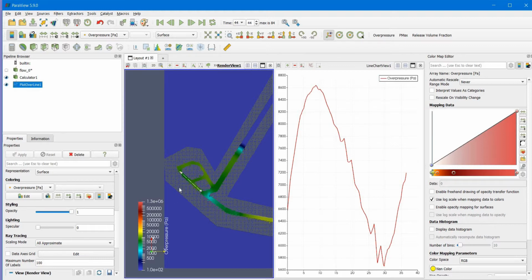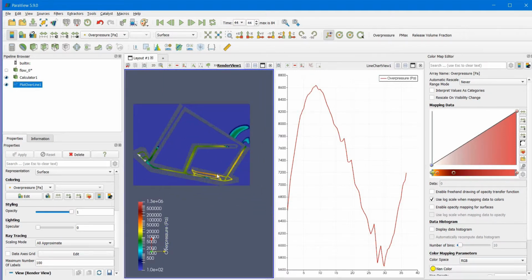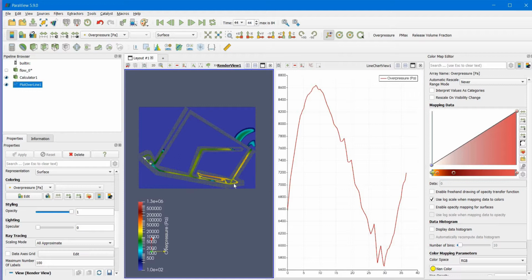But that's basically it. That's how to model a mine explosion. It's a complex process, but it's easily doable on exploCFD. These calculations took tens of minutes each. That's the advantage of using something like exploCFD, and you get pretty localized results, and you could go through the dispersion, the gas explosion, and finally the dust explosion.